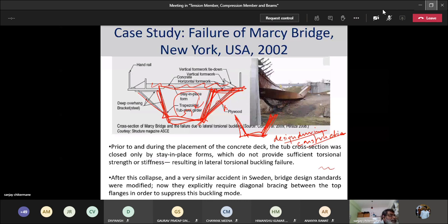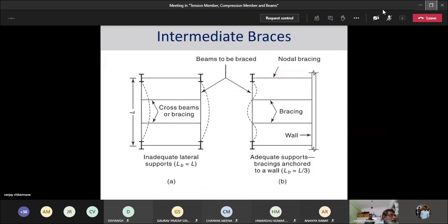The final sections of very many structures are safe, but during construction there are certain stresses which develop, which the system is unsafe for, and collapse can happen for those kinds of things also. So it's not just the final loads and stresses which need to be checked, but also the intermediate systems which generate failure.